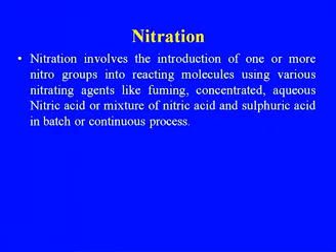Nitration is one of the very important reactions in the chemical process industry. Nitration involves the introduction of one or more nitro groups into reacting molecules using various nitrating agents like fuming or concentrated aqueous nitric acid, or a mixture of nitric acid, the mixed acid that we are using in the manufacture of TNT, trinitrotoluene. In many of the other chemical process industries we are also using the mixed acid instead of nitric acid. So that is also part of nitration.